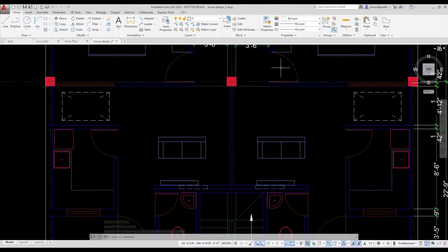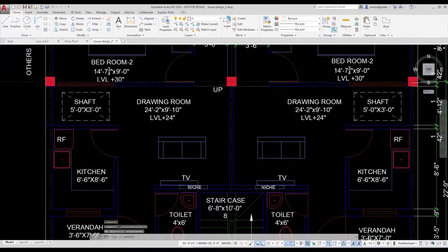I'm ready to restore the text elements, so I go back to the status bar. Notice that the Hide Isolate icon is shaded to indicate items are hidden. I left-click on the icon and select End Object Isolation. The text is now displayed.